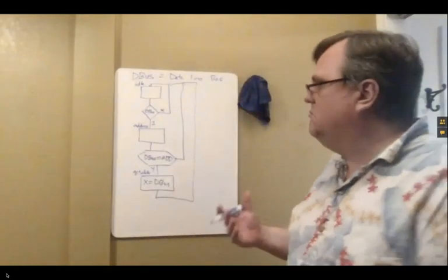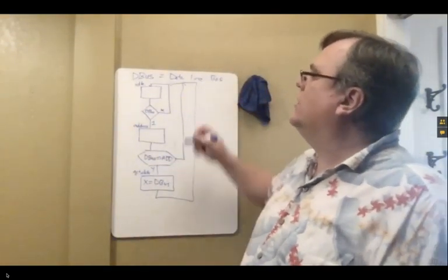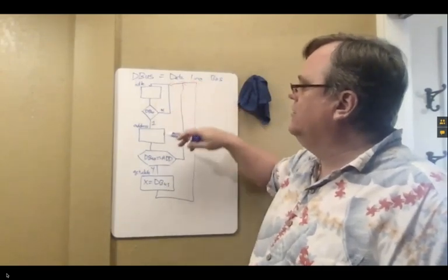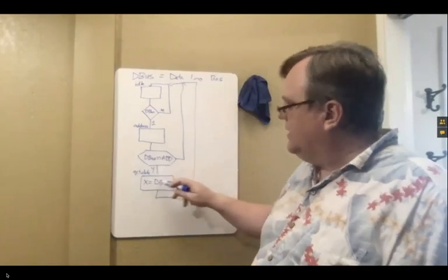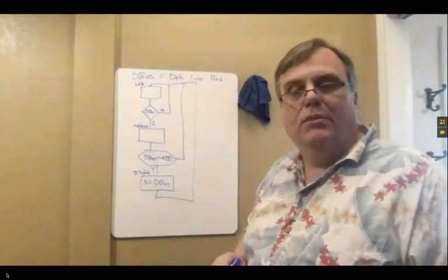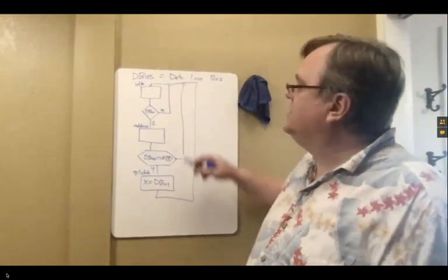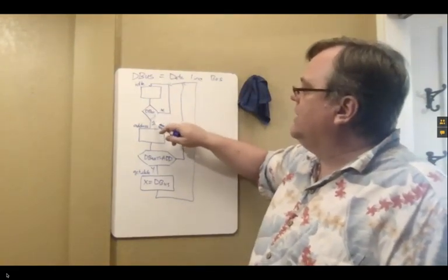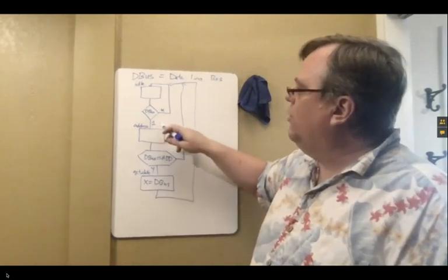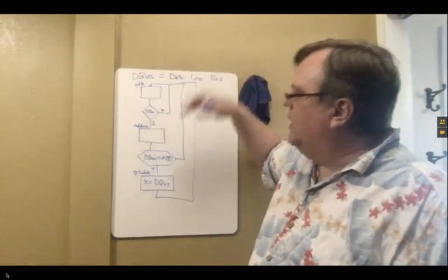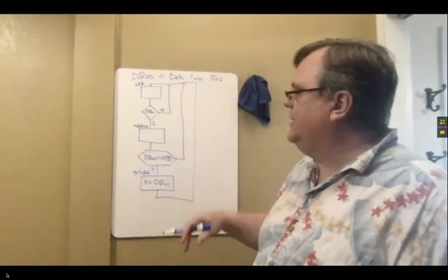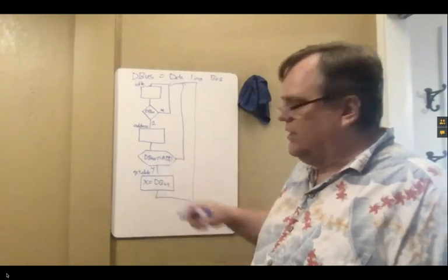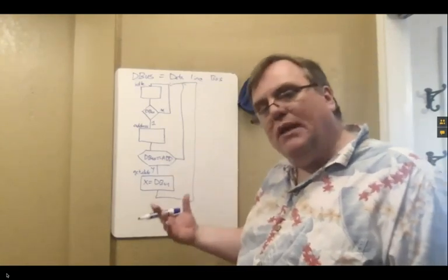This is a very simple bus, but it is a bus that can work. I've got an idle state. I wait for data. I check to see if it's me it's talking to. If it is me, I collect the data they send, and I come back up. So it kind of expects this signal of data bus as all ones to say wake up, address. Check to see if my address is the next piece of data that's on it. Collect data if it is. So does that make sense as a description to you?